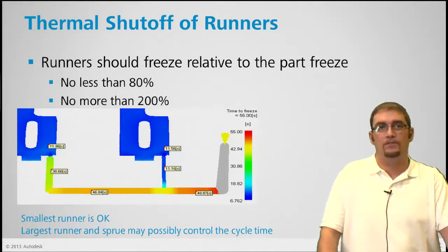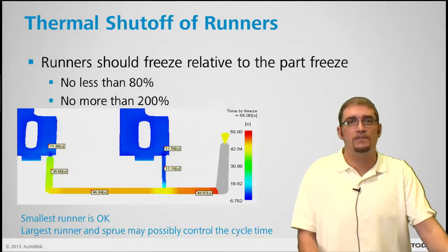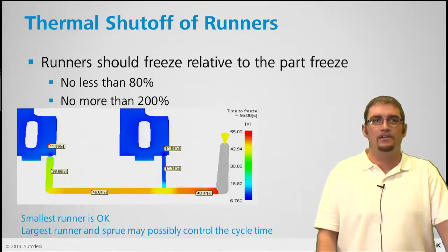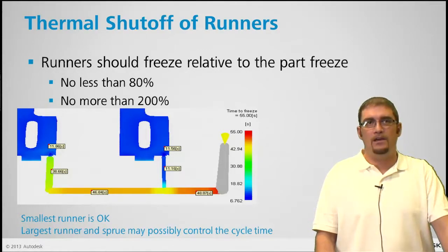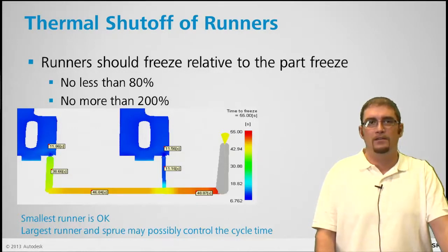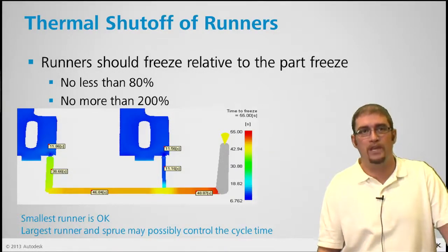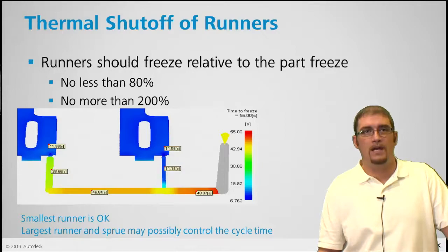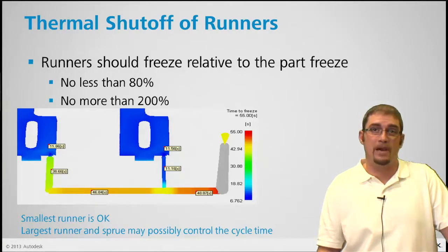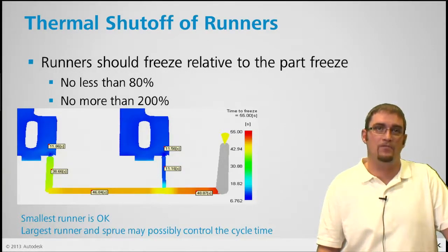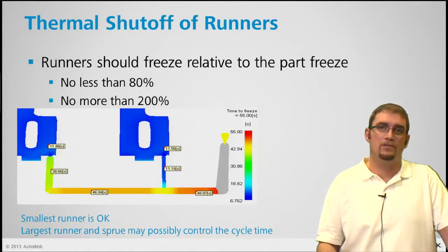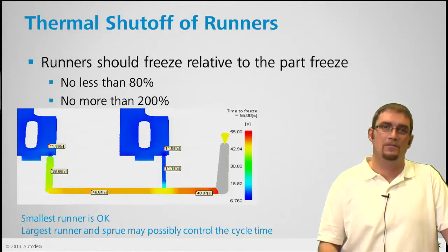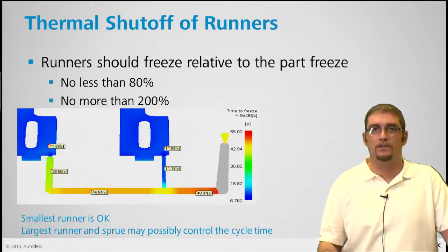Thermal shutoff, also gate freeze. This is something you want to keep in mind. You don't want your feed system to be any less than 80% of the actual gate freeze here, because what happens is you can run into packing issues. Your gate will freeze off before you can pack the part. And again, you don't want to go more than 200%, because then your feed system's going to start controlling your